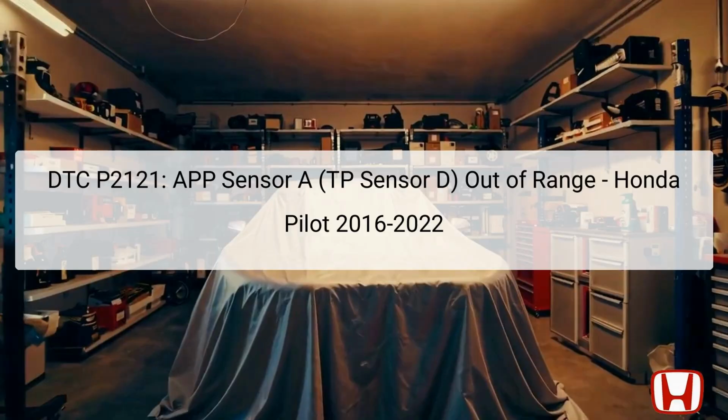Welcome to this diagnostic guide on DTC P2121 for the Honda Pilot models from 2016 to 2022. DTC P2121 signifies an issue with the Accelerator Pedal Position, APP, Sensor A, specifically noted as the Throttle Position, TP, Sensor D. This sensor plays a crucial role in monitoring the position of the accelerator pedal and sends this information to the Powertrain Control Module, PCM.